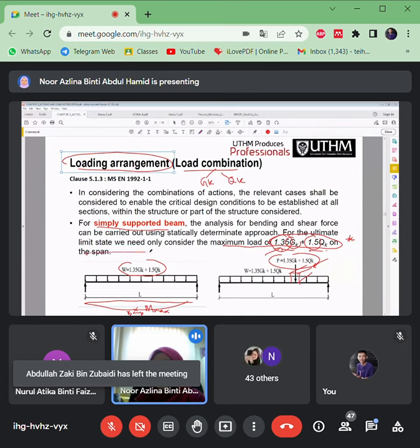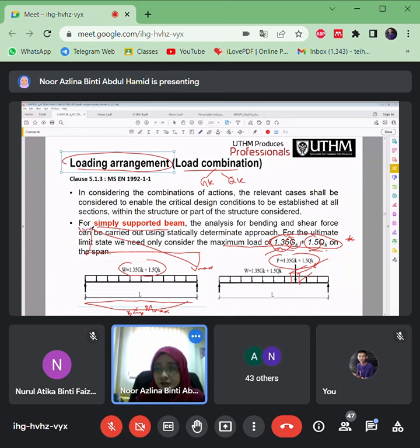And also come out with the shear force diagram. What is the Vmax here, either by equations or by reactions? What's the reaction for the supports according to the load that applies on it? Then you can plot the bending moment diagram and shear force diagram.